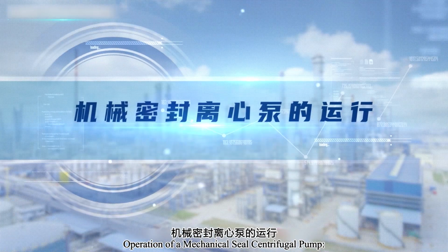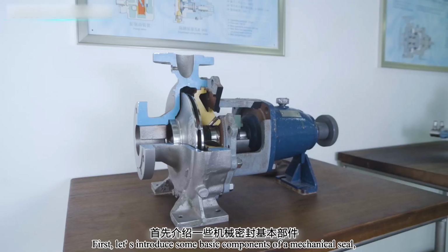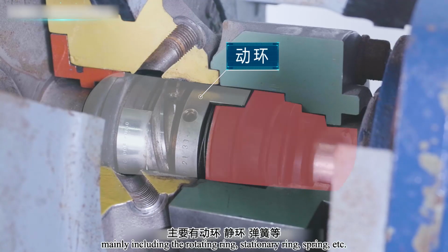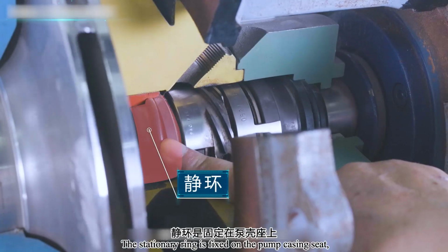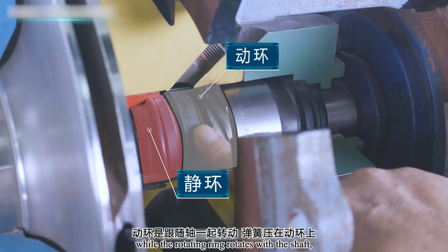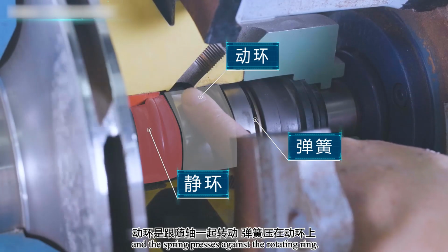Operation of mechanical seal centrifugal pump. First, let's introduce some basic components of a mechanical seal, mainly including the rotating ring, stationary ring, spring, etc. The stationary ring is fixed on the pump casing seat, while the rotating ring rotates with the shaft and the spring presses against the rotating ring.